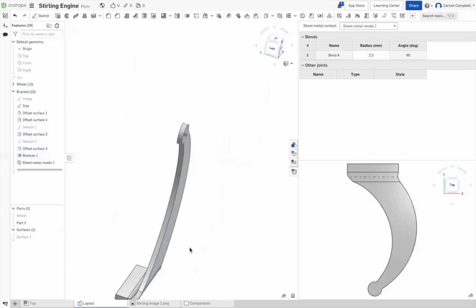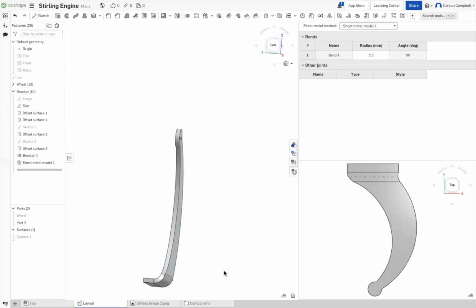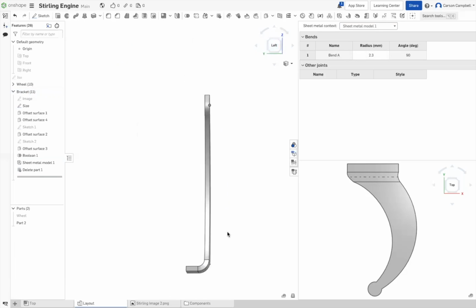Look, if you're going to get involved with surfacing, you're going to have these surfaces all over your model. If you work with my models, this is how I solve it. One of those icons up there is called delete part. Go up to your menu bar, just to the left, one more. Click that, go down and pick surface 1 below it. Say okay. So did we just use that temporarily? Yeah, they're temporary.